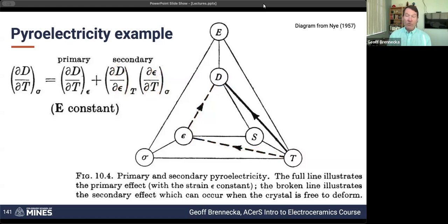And so in order to capture the entire pyroelectric response at a constant stress, so constant stress is relatively easy, you just don't touch it. And so the easiest way to keep materials unstressed is to have that stress be zero. It's possible to try and have a constant stress in some other manner if you've got a clamp on it of some sort where you can maintain that. But it's way easier just to make that constant stress zero.